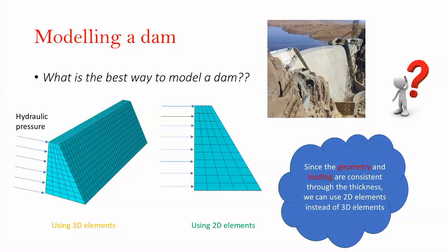I see. Most commercial finite element software like Abaqus, COMSOL, or ANSYS have only simple tools to create the geometry. That's why people usually use SolidWorks or CATIA to create the geometry, or even create it from microscopic images or CT scan images, build the 3D geometry and then import it into the software. I see. All right.